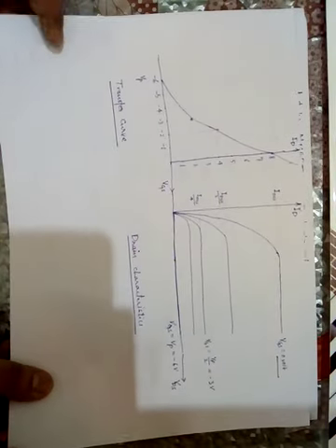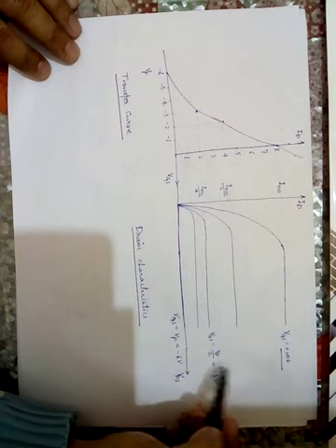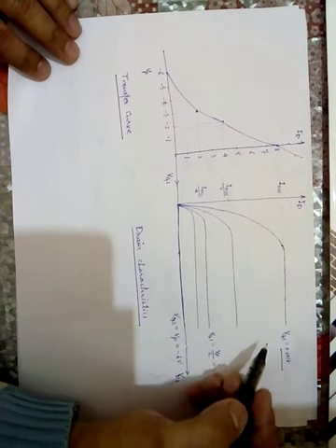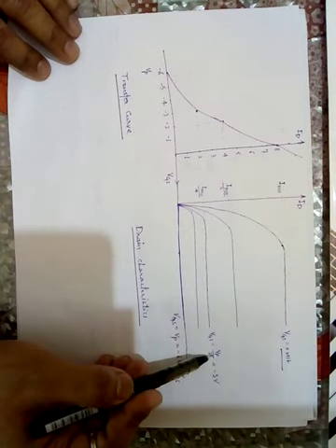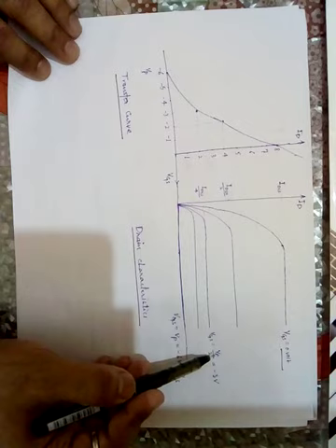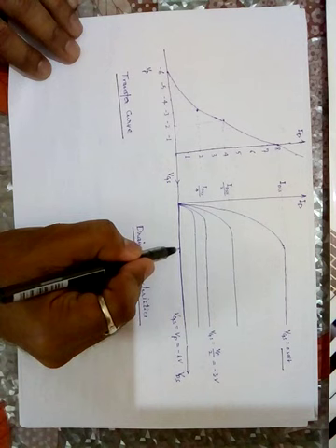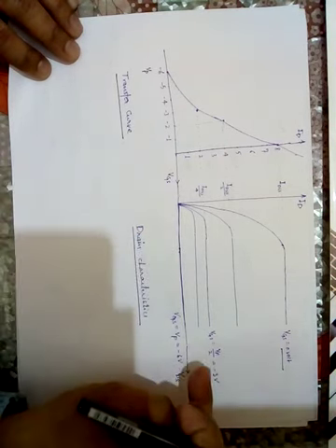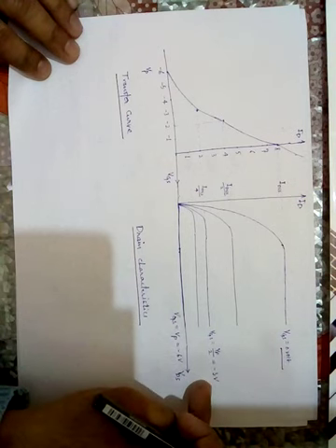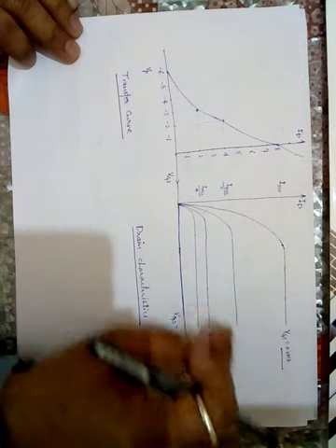Otherwise it's just like a JFET. On the basis of that, we increase the VGS in the negative direction. We can see the number of plots I have drawn here. Here VGS is equal to VP divided by 2. This is the pinch off voltage. Pinch off voltage is -6. So VP by 2 is -3 volts.